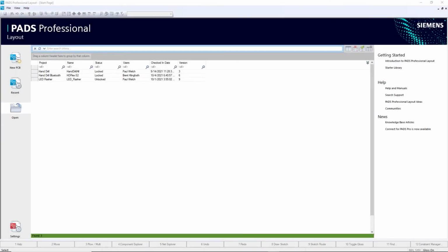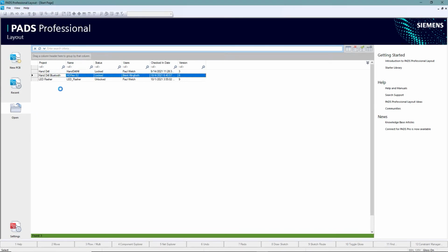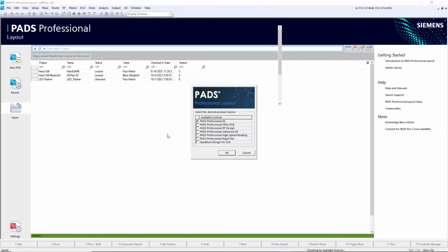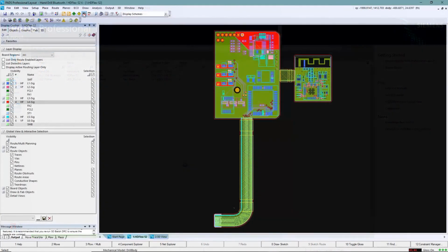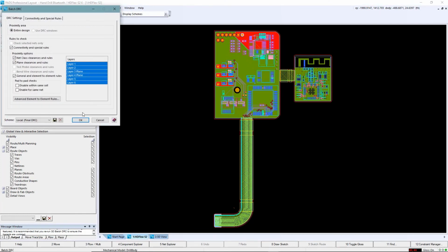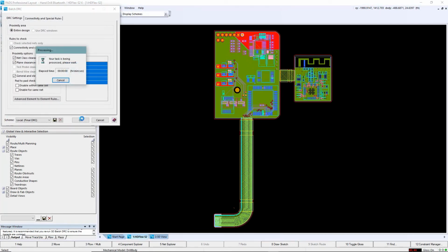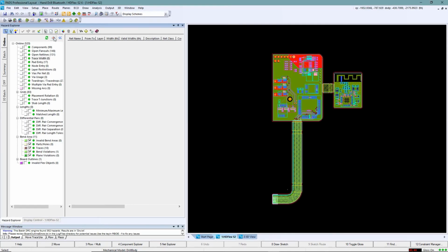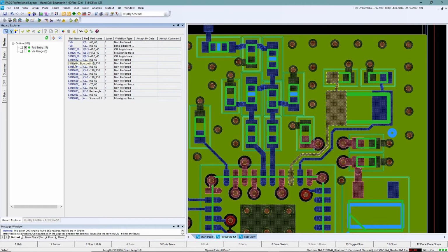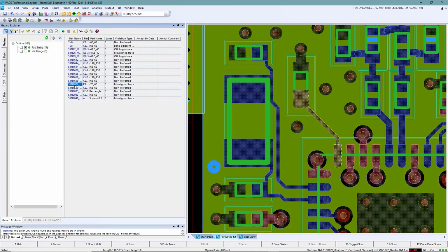Alright, we've come back into work after checking our design the night before, so we need to check the design back out, and we'll finish our DRCs up and go ahead and output our fabrication data. From the main toolbar, we'll go ahead and activate our batch DRC. You'll notice that it'll already come up pre-configured because for our batch DRC function, like many other features within PADS Professional, you can create schemes so you're not having to readjust everything on the fly.